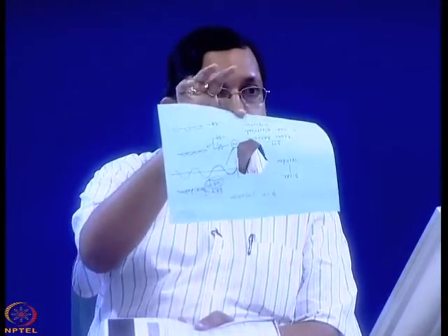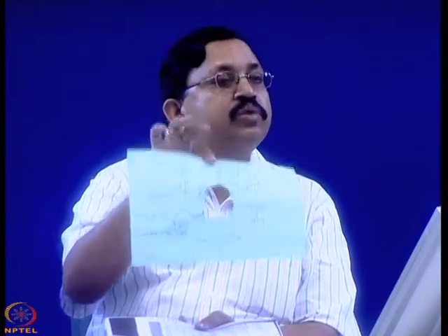The area of the device, if the diameter is say 4 centimeter, then the radius is 2 centimeter, so it will be pi r square, that means pi into 2 square area will be the p-n junction, not the whole surface. Say it is 10 centimeter by 10 centimeter or 100 centimeter by 100 centimeter, you only define the area where the p-n junction will take place, and that will be the effective area of the device. Because in many calculations you will find a term A, area. Area of what? It is not the surface area, it is the area of the device. Yes, do you have any question?